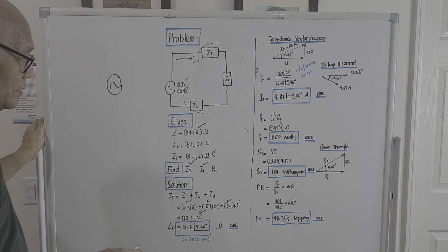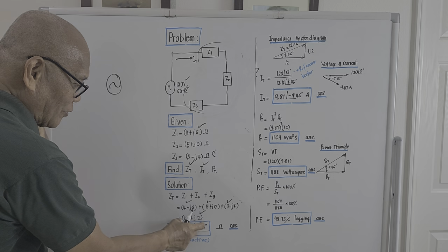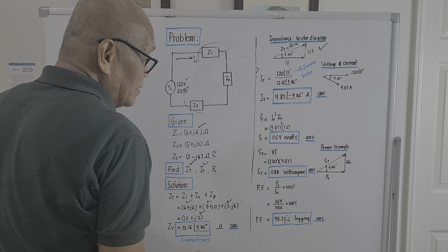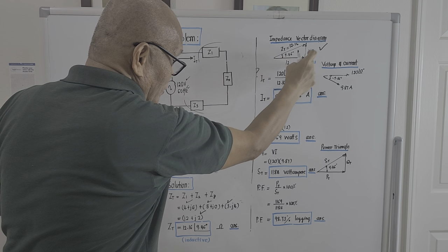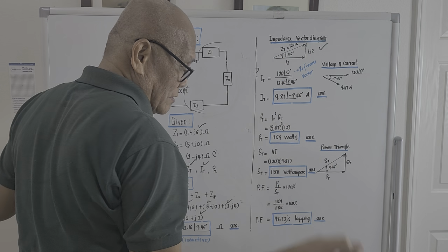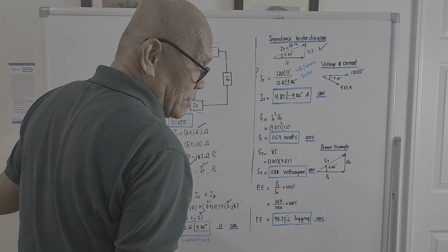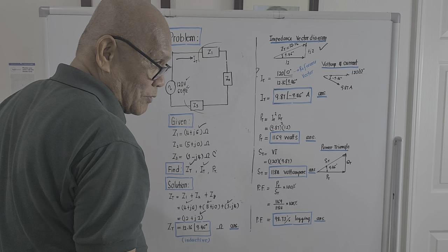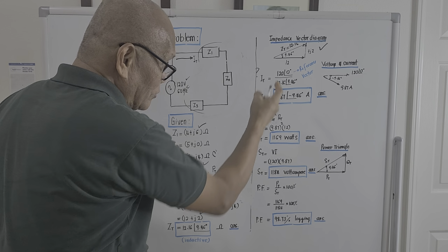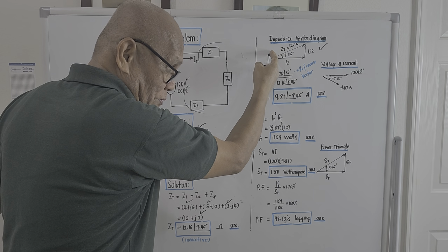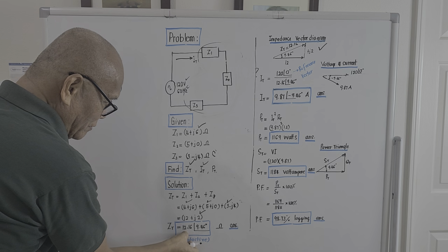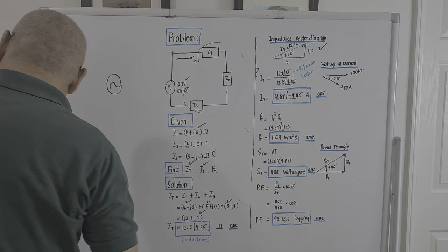okay? And if we try to bring out the vector diagram of this one now, the real part is 12, imaginary part is 2. So if we try to compute for the magnitude of the impedance, okay, trigonometry. You could either use Pythagoras principle or use the definition of sine and cosine to get the hypotenuse. So in here, Z total will be 12.16 angle 9.46 degrees.